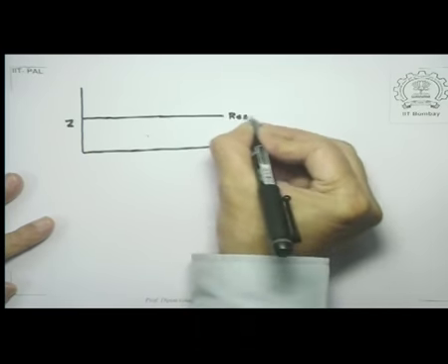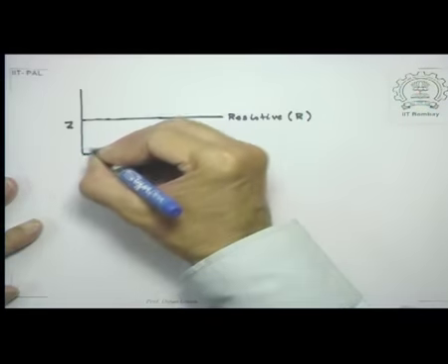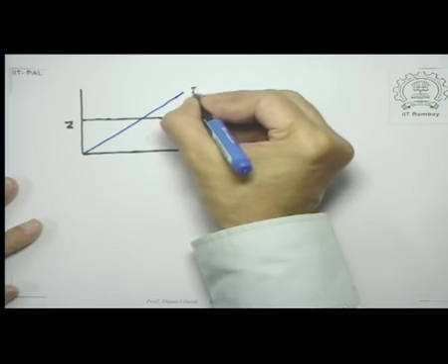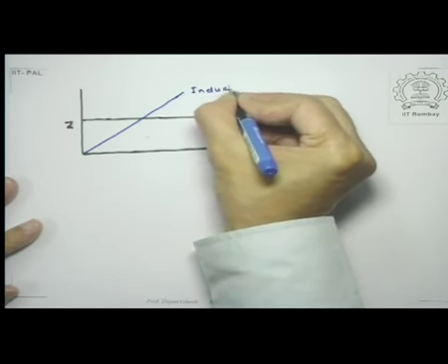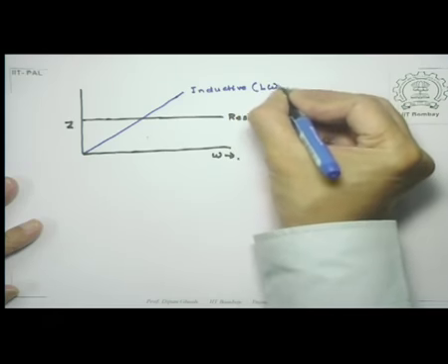So this is simply equal to R. For an inductive circuit, the impedance, which is the inductive reactance, is equal to L times omega, so it increases linearly with increasing frequency. So therefore, this is for inductors. L omega is the Z.